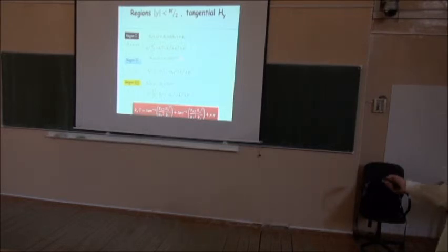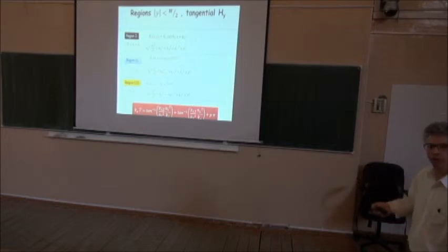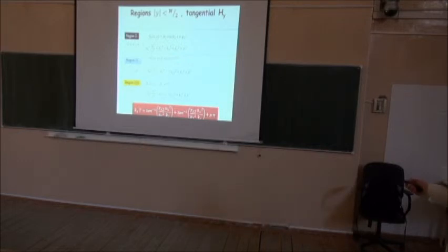So with those definitions there, this structure is identical to what we had before for the slab waveguide, and that is when we have the TM mode. So we know how to proceed. We do exactly what we've done before, and it's straightforward to calculate the dispersion relation that we had before, and we know that the thickness here of my guide is T, so that's what shows up on the left-hand side.